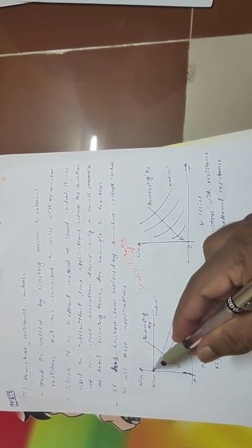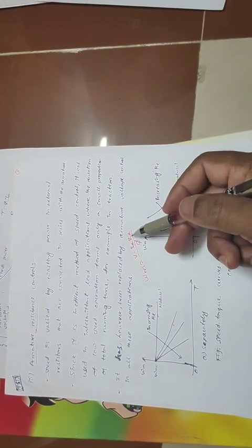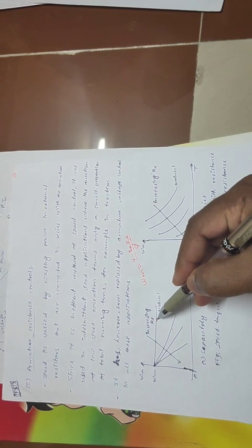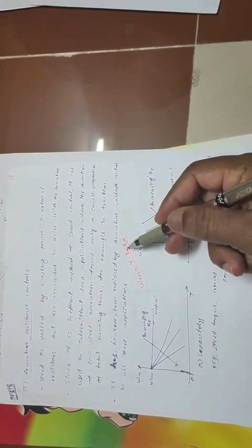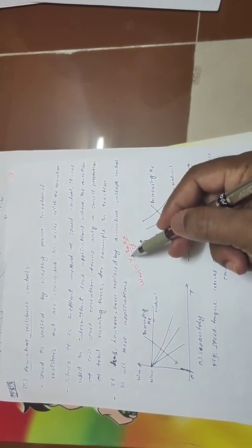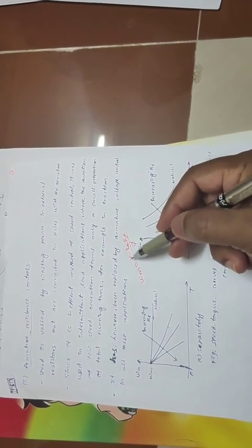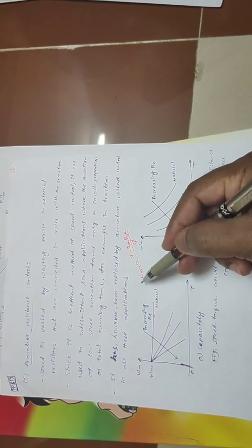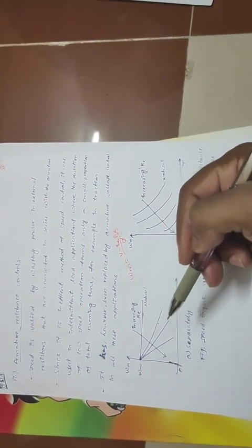Initially the characteristics will start at the same point, because as per this equation, as the Ia Ra drop is increasing, your speed will reduce, because it is V minus Ia Ra, right? This drop is increasing, which means the overall numerator will decrease. That will decrease the speed of the motor. So that's what it shows here.